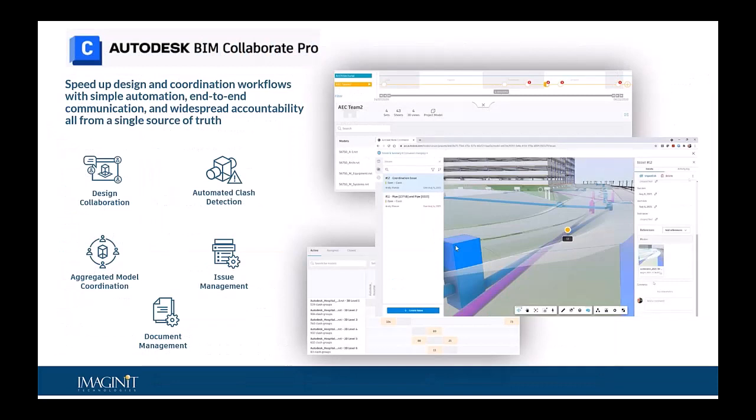And here's just kind of a view here where the utilities are under the ground. You can see a parking structure, but here you can see where you have storm pipes or gravity networks crossing and having an issue here with a clash, right? So that's going to need to be addressed. So the key thing is being able to do this information and review these clashes and detections. And when you start having these models and doing that, being able to have those models up in the cloud and being able to verify that information before you get out in the field.